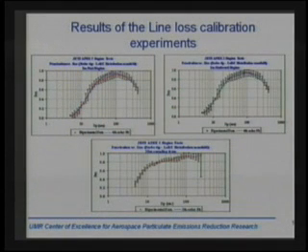When you're doing extractive sampling, we have to worry about the possibility of losing particulate matter as we draw it into the sampling system and transport it to our instruments. The instruments, for safety reasons, have to be mounted beyond the limit of the wing on the aircraft. Depending on which engine we were sampling from, there are different lengths of line from any given probe. What you see here are penetration plots for particulate matter as a function of size, depending on where you're sampling from. This was the port engine and the starboard engine, and here's the 50-meter sampling probe.